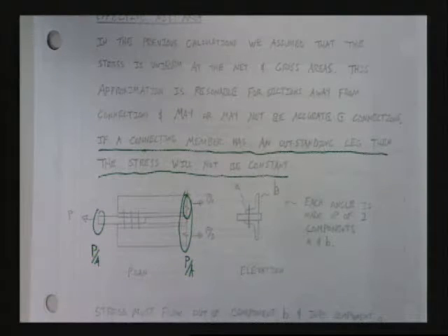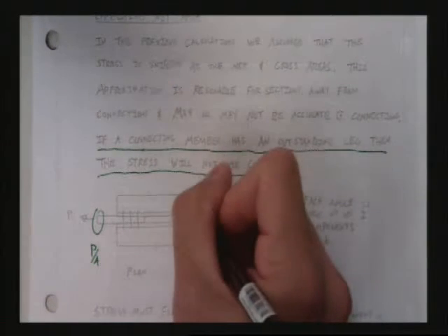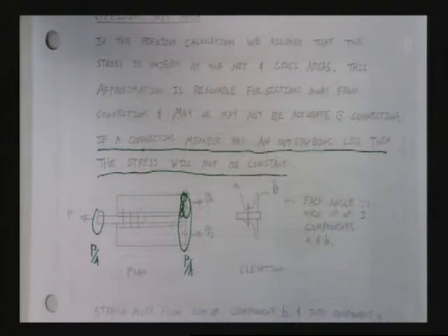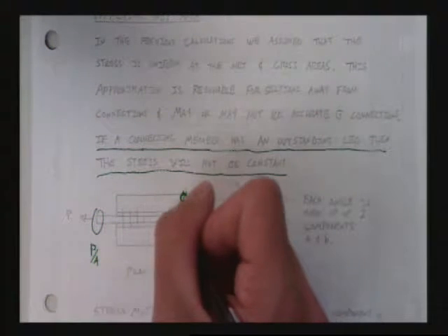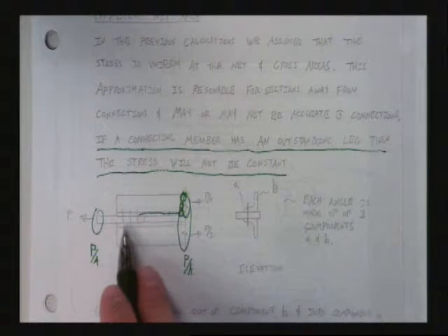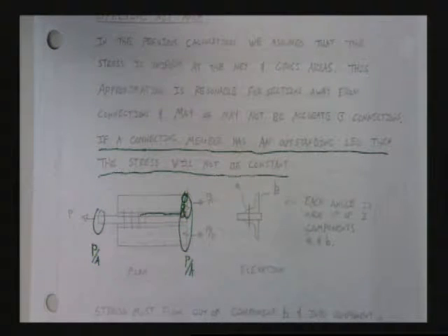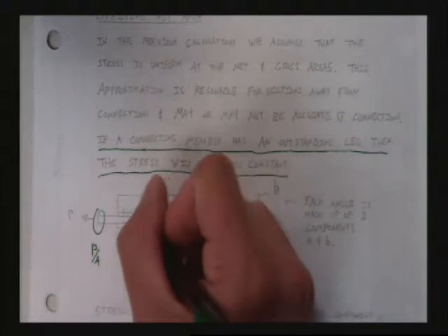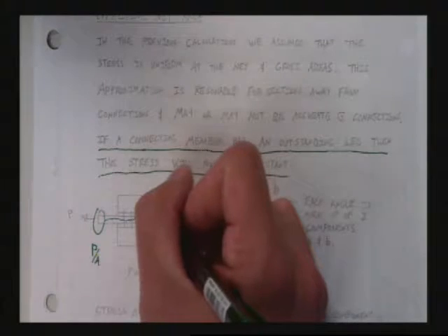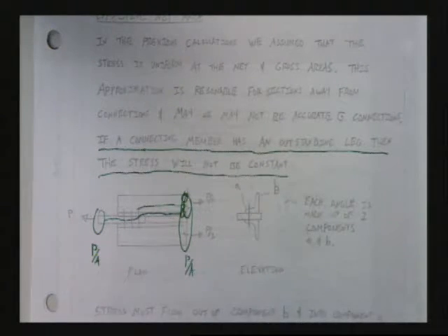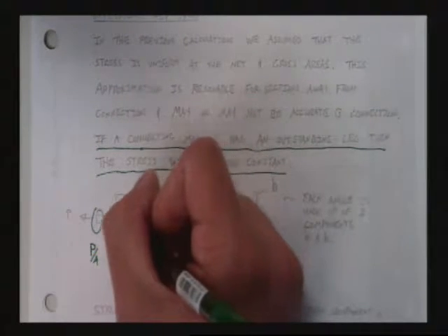Let's think of it as water. Let's become the stress. Let's become the force. We'll break this force up into 3 chunks, or chunklets of force. Take the chunk of force at the bottom. It's running, think of it as water, and all of a sudden it sees 3 possibilities to leave the cross-section. This force is like an 18-year-old ready to get out of the house: I'm out of here as soon as I possibly can. So it's going to run through this bolt and go down at the bottom. You with me? This one comes down and says, you know what? I like staying at home a little bit longer. I'm going to take my time leaving, and I'm going to do some here.